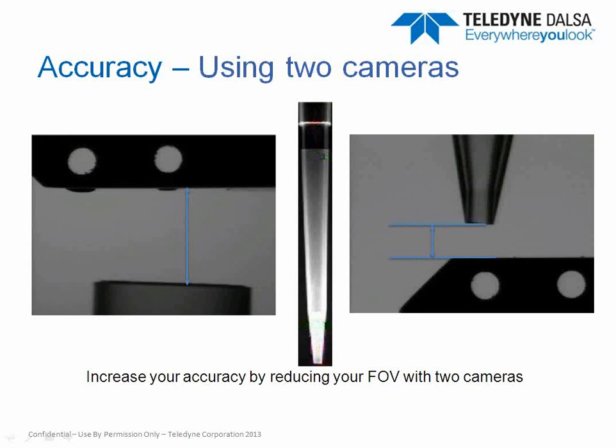So if you use 2 lower resolution cameras with a calibration mechanical piece that you know the exact distance, then you capture the top of the pipette, the bottom of the pipette, you measure the offsets from those calibrated pieces, and then you get a really accurate measurement. Again, instead of trying to measure a 3-inch field of view and waste a lot of area. People have done it too with drive shafts, wheel bases that are so big, and they really don't care much about any of the metal part, just at the ends how accurately they measure.